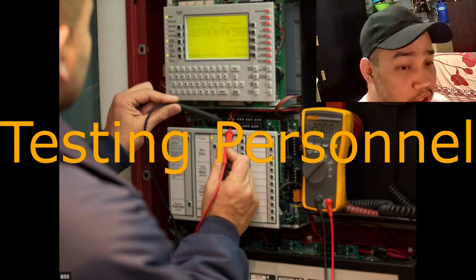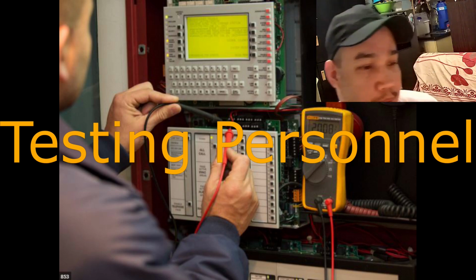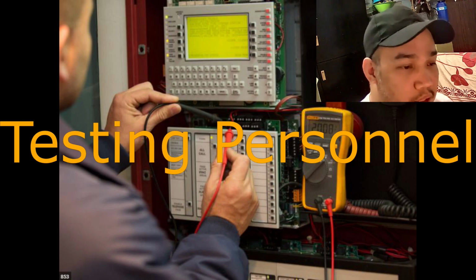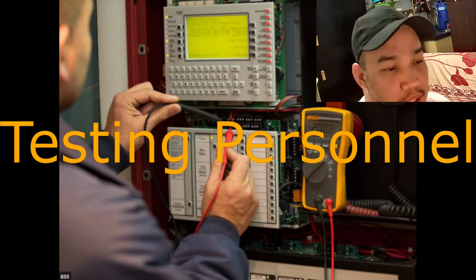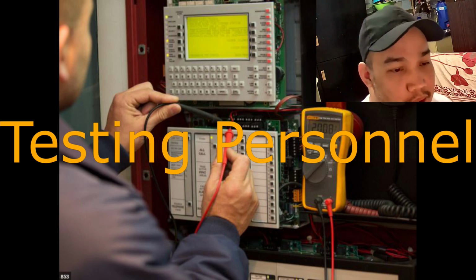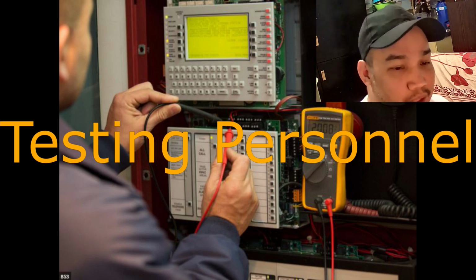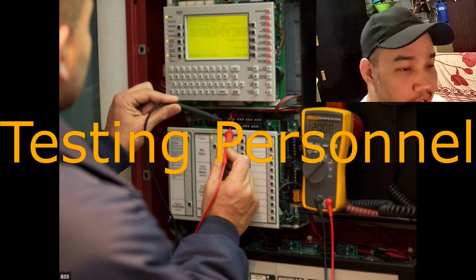The job was easy initially, after we successfully tested the integrity of existing cables, and we were good to go for replacing all the devices. But the challenge came when we finally worked on replacing the fire alarm control panel. At first, I thought that we'd just dismantle the existing panel and install a new one. Terminate the wires, done. But when we removed some cables terminated within the panel, too late I realized that the power plant was at full operation that day, which led to activating its fire safety interface to the conveyor, and it stopped the plant operation.